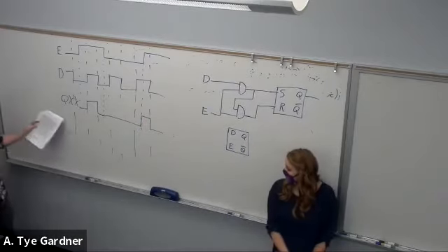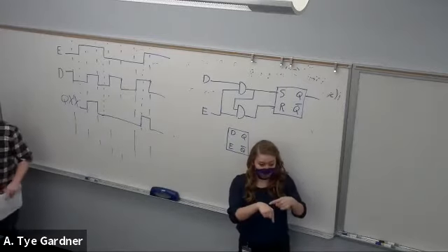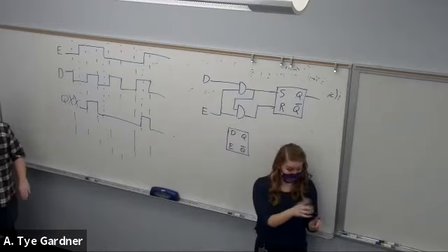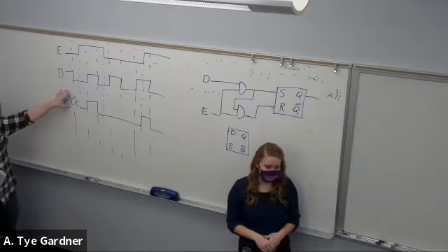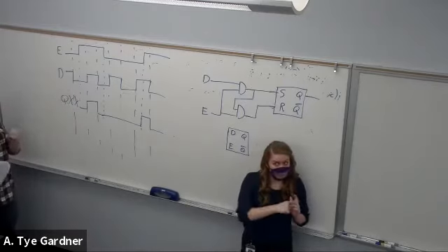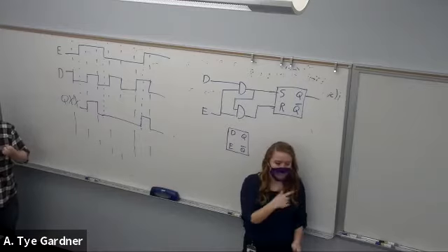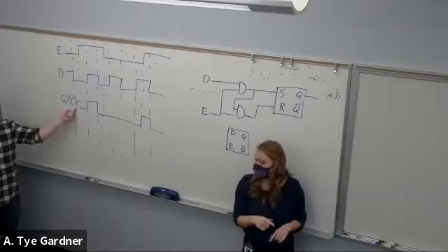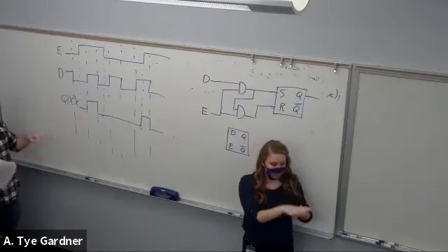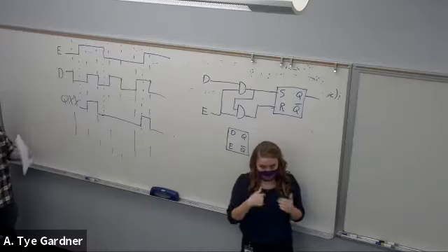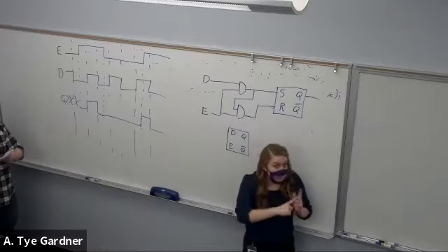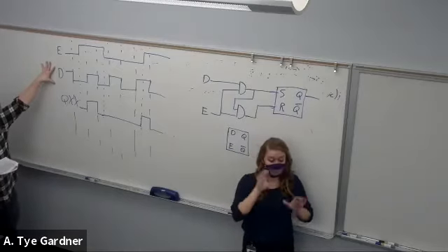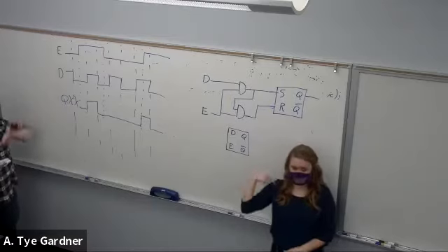Right, and then Q bar is just the opposite of that. And the opposite of don't know is we still don't know, right? I wouldn't fault you if you made an assumption, say, it starts at 1, I guess. And I'll try and communicate if I want you to do the don't knows. I would default to this to illustrate that you know that it's don't know, right? And sometimes I'll say, assume that it starts at 1, and so on and so forth. So this is how we use timing diagrams to illustrate what's happening with these circuits.